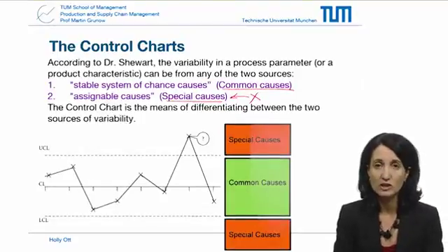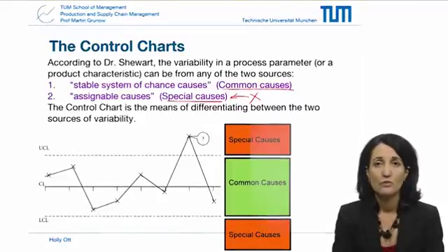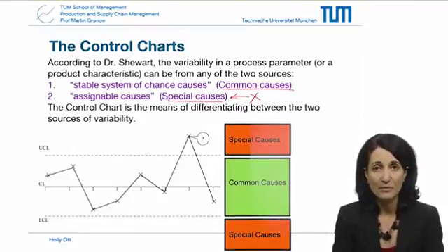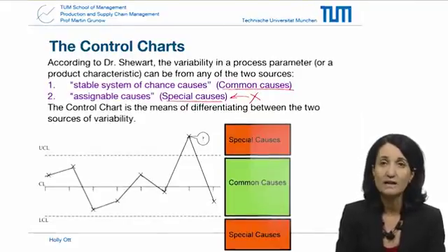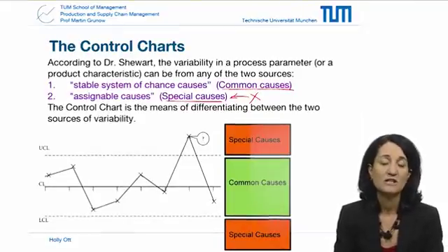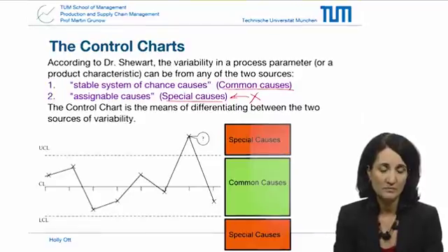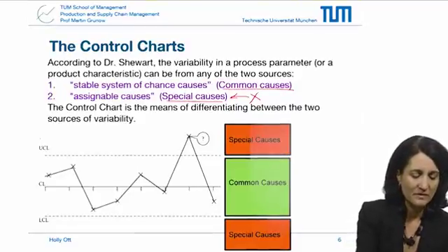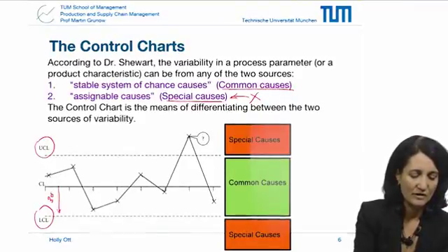So we learn to look for these special causes using a control chart. We would take a sample of a stable process and we would calculate some kind of statistic. And we would look particularly at X bar and at R. From this sample statistic, we would construct 3 sigma control limits for that sample statistic.